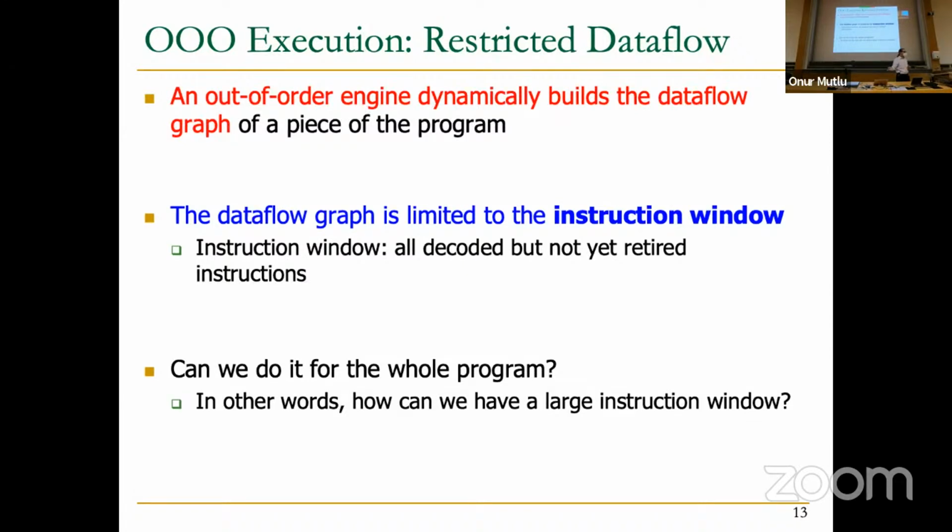You mean branch prediction? You mean branches? Yes, we will handle that. Basically, if you have a mispredicted branch, you need to flush the entire machine. But it's not a problem if you correctly predicted that jump. If you correctly predicted the branch, then you've already fetched the instructions that are on the correct path. But if you mispredicted, yes, you get rid of all of the work that you've done.